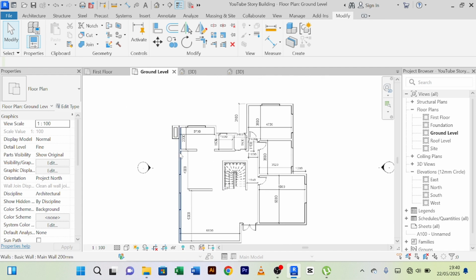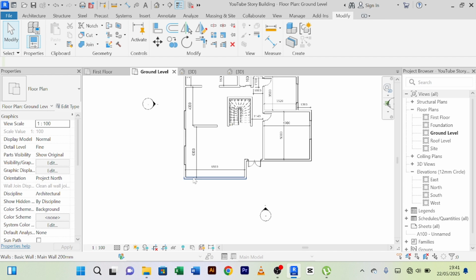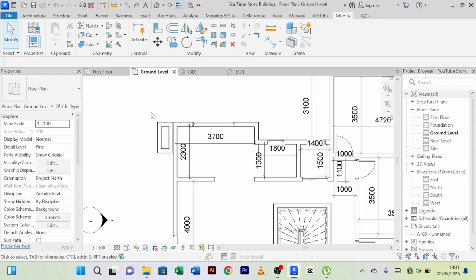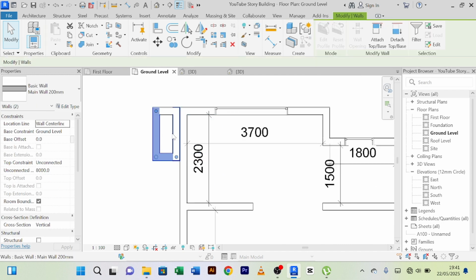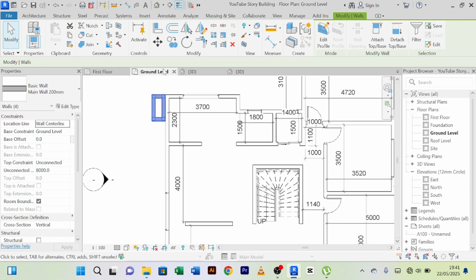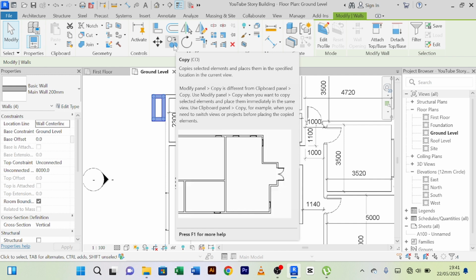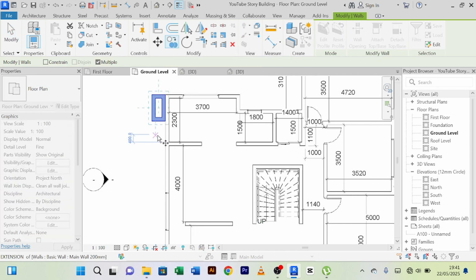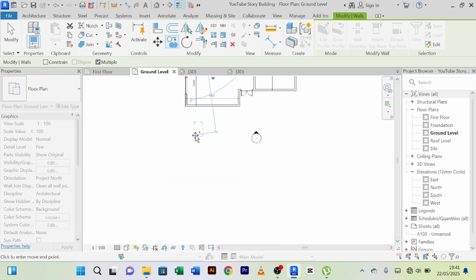Now from here we need to align it using the line tool so that we don't get into trouble with Revit. So I've clicked on my line tool. I'll align here, then I align this. I'll escape one. I'll align this to this. Let me see, this to this.